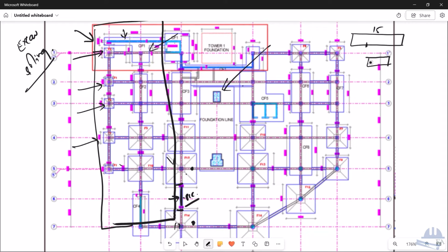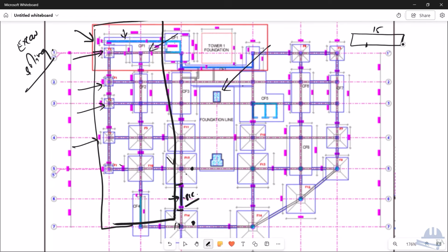So what you do instead is make sure that excavation is done, and after that there is at least 1 day more for the soling. Let's say excavation finishes on day 0, reference 0, and the soling should at least go to day 0 plus 1, or let's say 2.